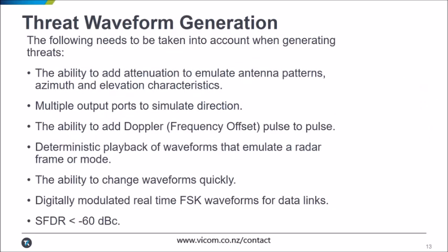As you can see from this list of requirements, programming AWGs can require many changing factors. The ability to generate signals with very low noise and clean, spurious-free dynamic range is critical. Many test scenarios also include being able to capture specific reflections from a dedicated receiver and store these signals that can be manipulated and played back to replicate specific situations. To simulate complex moving threats, the waveforms must be dynamically controlled by the test system, and new methods are being developed to make this easier.